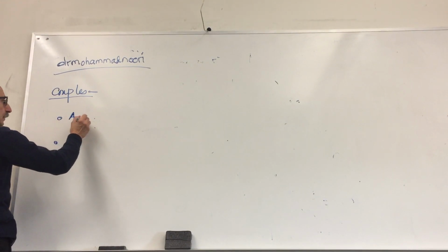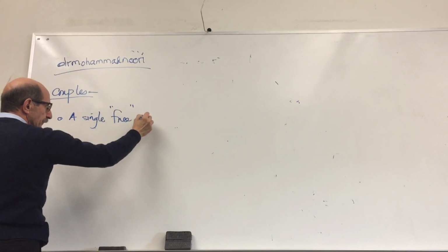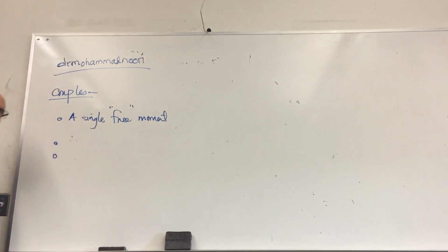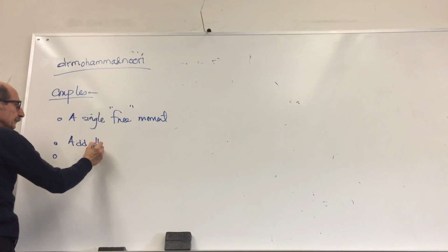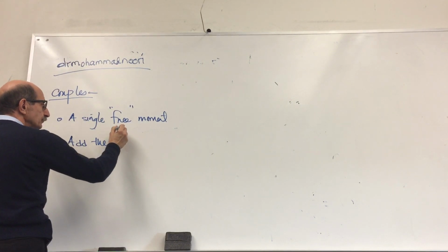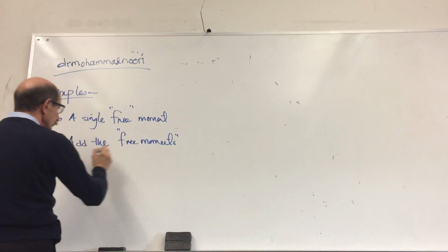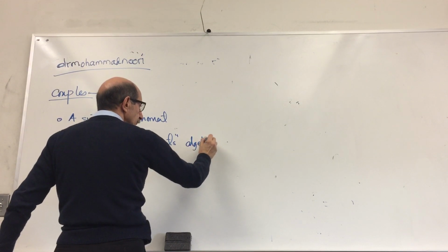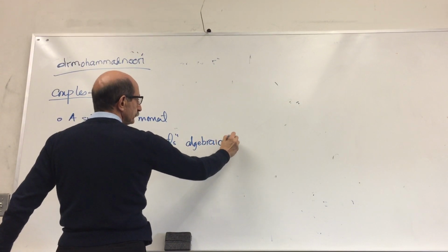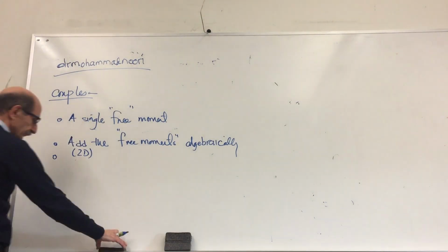Only a single free moment that you can put anywhere on the structure and does the same thing. And if you have several couples, you can just add the free moments, right? In the 2D case, of course, just algebraically. If they're 3D, you just add them up, like just a bunch of moments, okay?